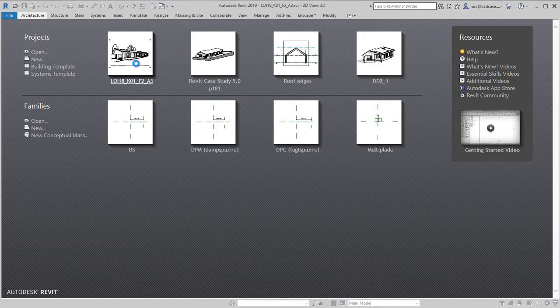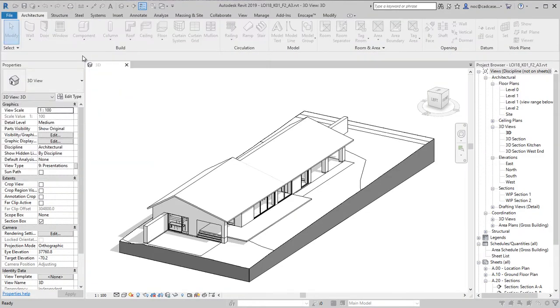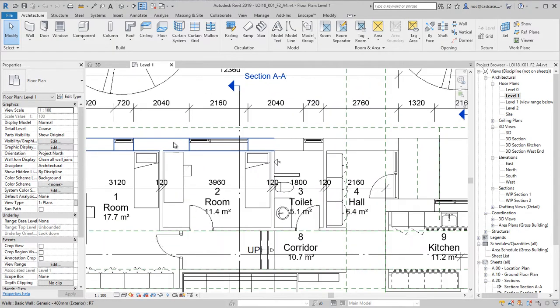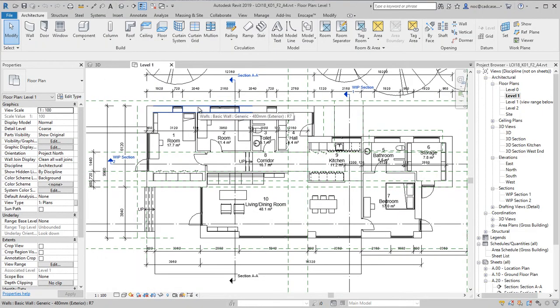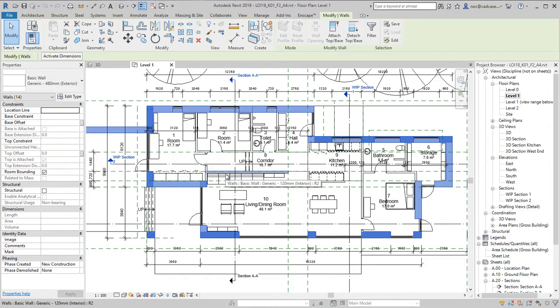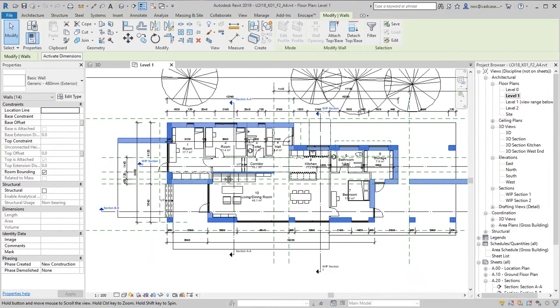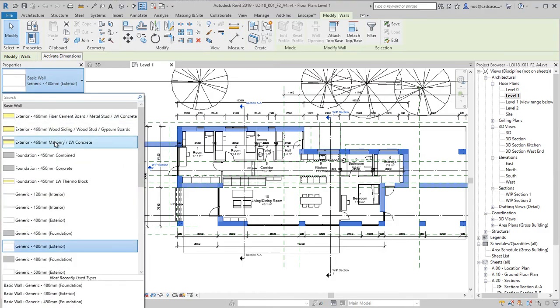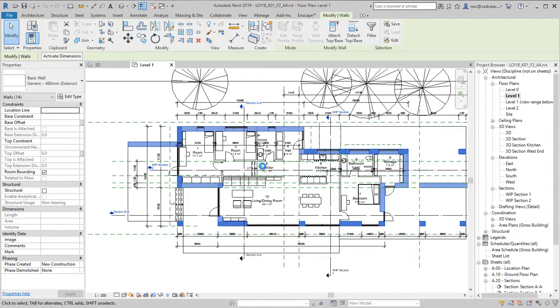Going into the scheme design, we start by opening the outline proposal phase model and save this as a scheme design model. In this phase, we begin to have an idea on the different building parts in the project. For example, the exterior walls that we have here. I start by changing these walls to a more specific building component. We'll have bricks, exterior, insulation, and then a lightweight concrete wall inside.